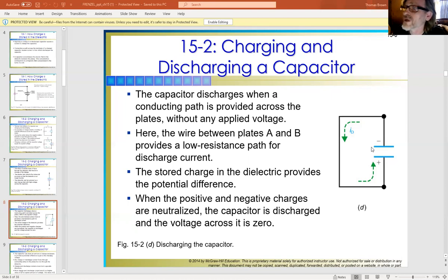Because it would literally store that charge. You figure somebody yanked this assembly out of a machine somewhere, it could have been down in Arkansas or Arizona, and they sent it back to the repair center. The time involved is well over a week, and this thing's still fully charged. It hasn't discharged at all. Oh my God. So you always have to be careful when dealing with these things. If it charges up and has not been discharged, that voltage potential will be sitting there waiting.